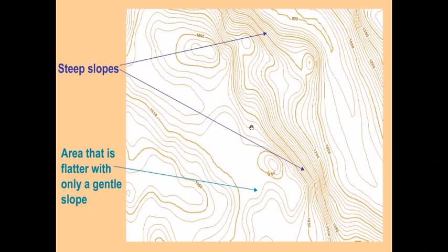Something that we've discussed so many times is that when you have steep slopes, the contours will be closer, and when the land is flatter, the contours will be widely spaced, and you can have these empty spaces in between. That means that the land probably over here is of such elevation whose contour line you decided not to draw. And that basically means that the land is pretty much flatter. So you get an idea.